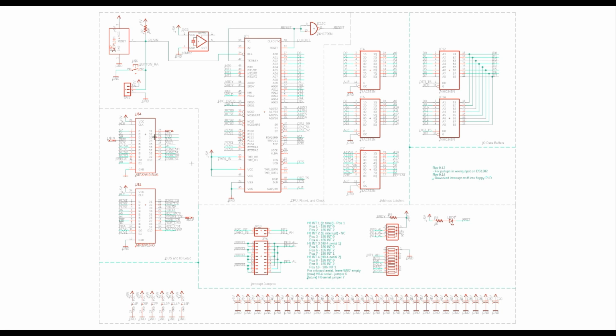Now there's a couple PLD sections that have the logic that drives all of this bus and addressing. So first we have this one here called the bus PLD, and it looks at the CPU state bits, some memory selects, the bus high enable and the bus low enable. Recall that's the same as A0. The data transfer enable, and the ALE. And it will generate the RAM and ROM chip selects, an M1 signal, and these D high and D low that run these two addressing selects here for multiplexing the 16-bit data bus down to 8 bits.